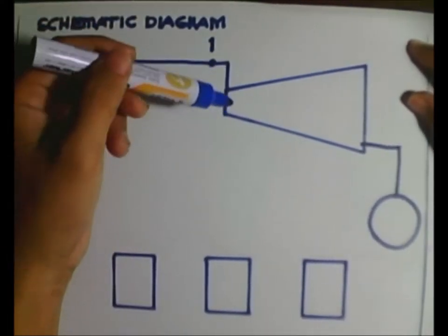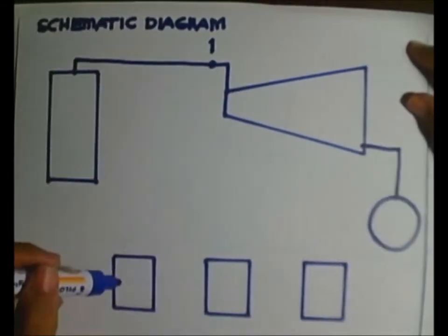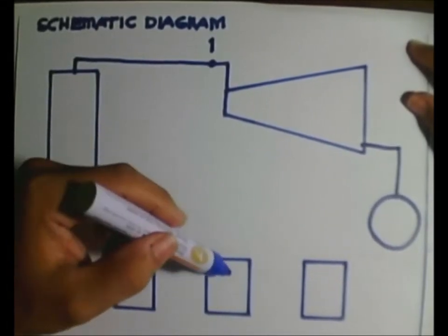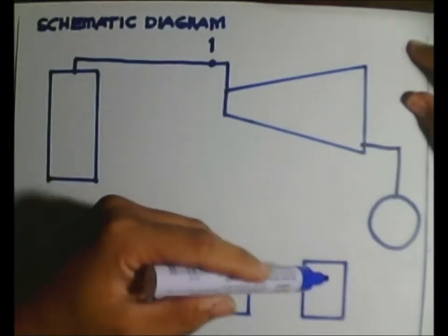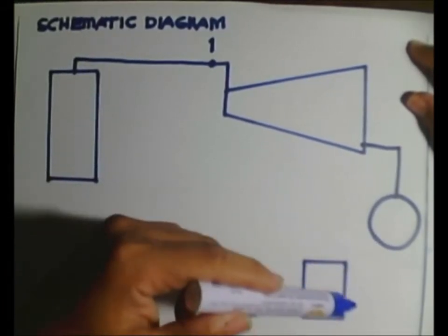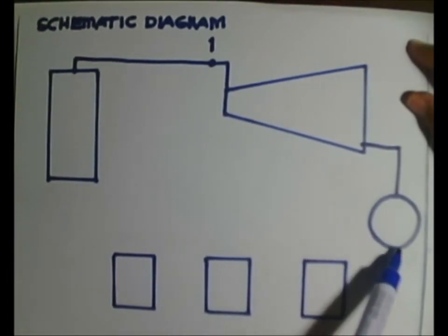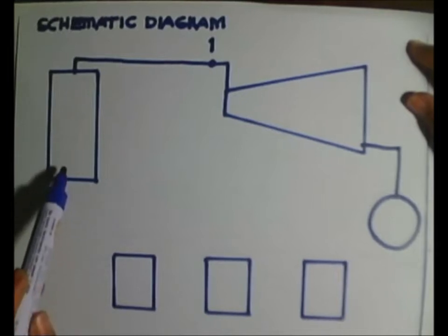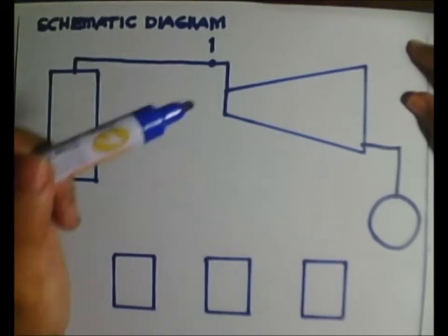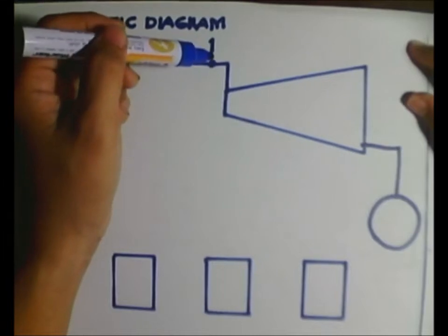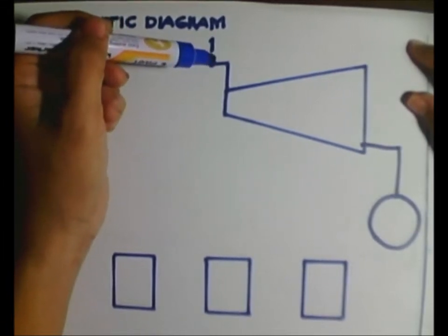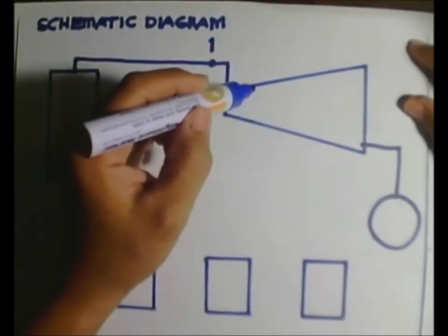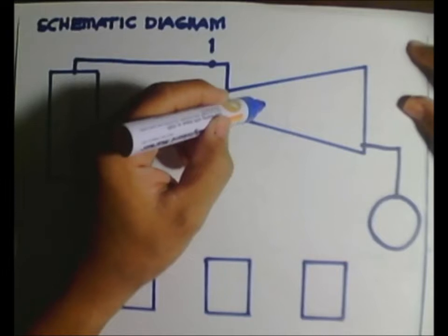but we notice here that we have open heaters included in our cycle, so that the purpose of these open heaters is to provide gradual reheating of the saturated liquid that comes out from the condenser towards our boiler, so that instead of the usual expansion of our steam from 1 to this point here, we are going to make extractions, say at this point here.